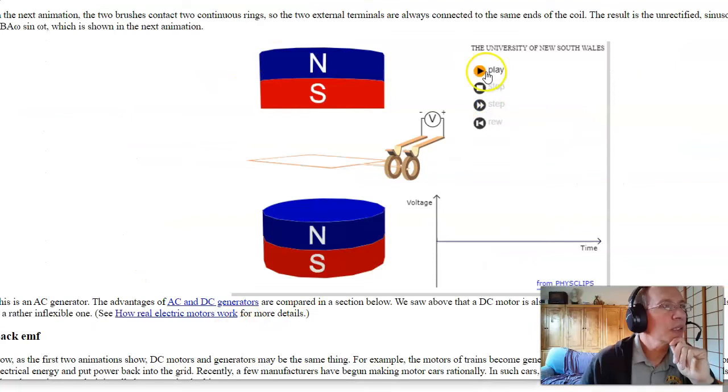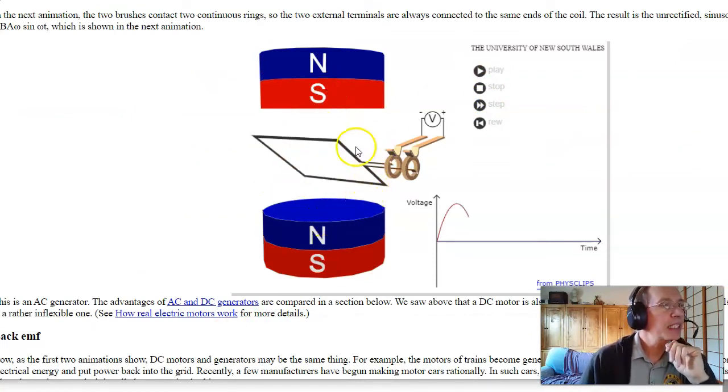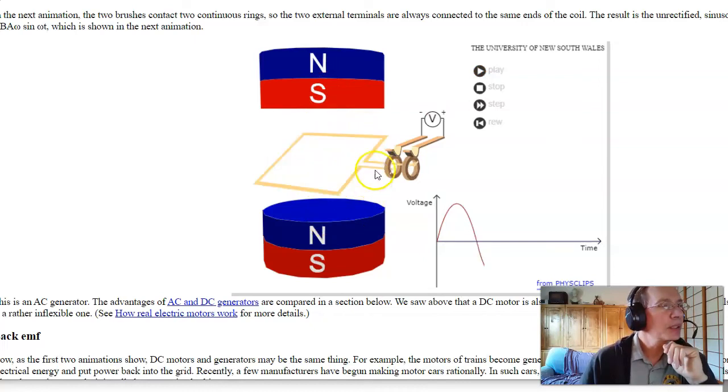So a little bit of background on motors. Back from physics, if I have a magnetic field and I put a coil, spin the coil around the magnetic field, the voltage induced is proportional to the number of windings times the change in flux, dΦ/dt.